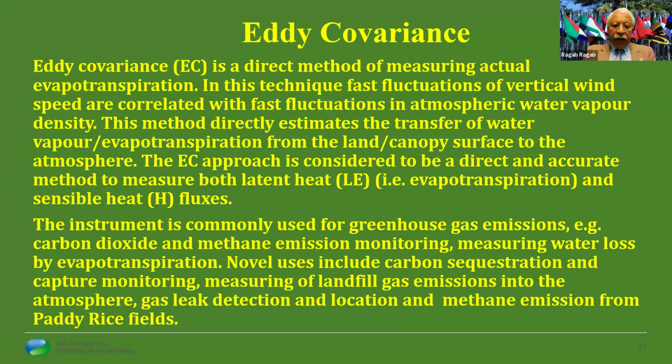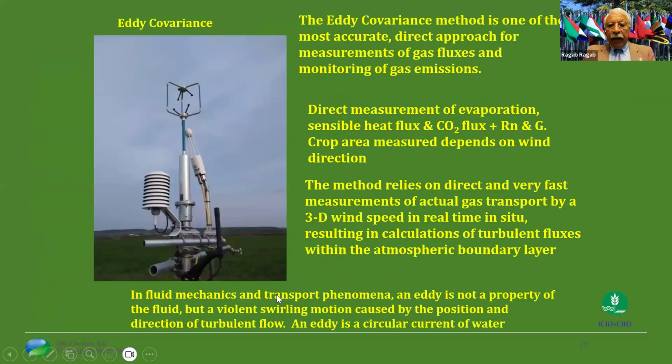This instrument is commonly used for greenhouse gas emission, carbon dioxide and methane emission monitoring, and measuring water loss by evapotranspiration. Nowadays there is also a novel use that includes carbon sequestration monitoring, measuring landfill gas emission, atmosphere gas leak detection and location, and methane emission from flooded fields.